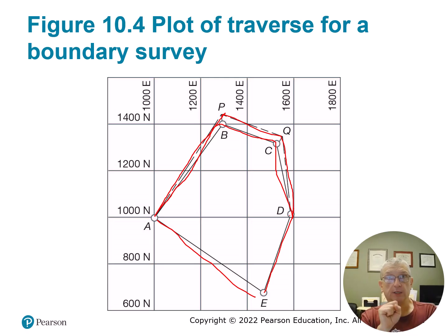Because if we locate a property corner A from traverse point 1 and we traverse 5 traverse legs down, and then from point 5 we locate the other, the iron pipe or the concrete monument at the other end of that property line, and it's B, then we determine coordinates for A and B, and then we will inverse the bearing and distance between A and B, and that's the bearing and distance that goes on the plat. So that's part of what we're doing there.